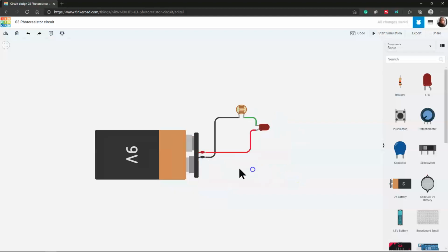What this circuit here is, just like in the notes, it showed you a schematic diagram of setting up a whole circuit where you had an LED and you had the photoresistor in place, and showing that you could play around with it and set up a circuit that would fade the light based upon input from this little photoresistor here. The point again is to demonstrate that everything we're doing with a controller, you could build a direct circuit to do exactly what you want, but the Arduino controllers that we're using allow us to have it be reprogrammable.